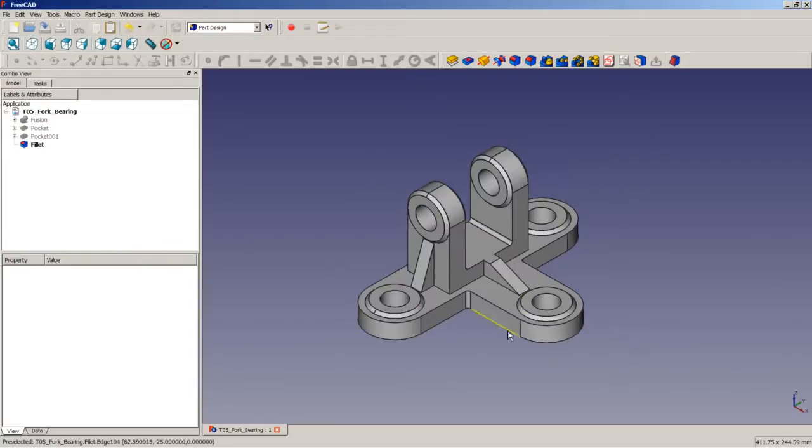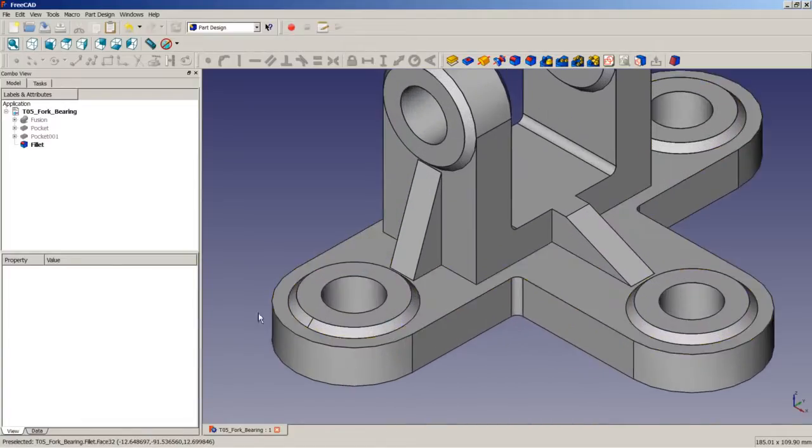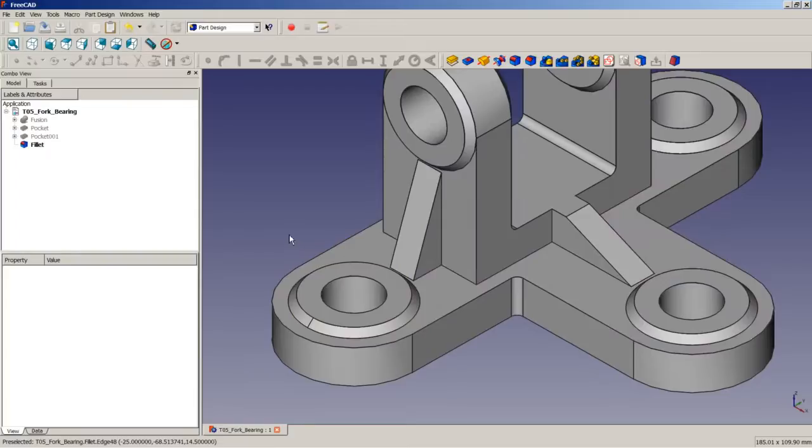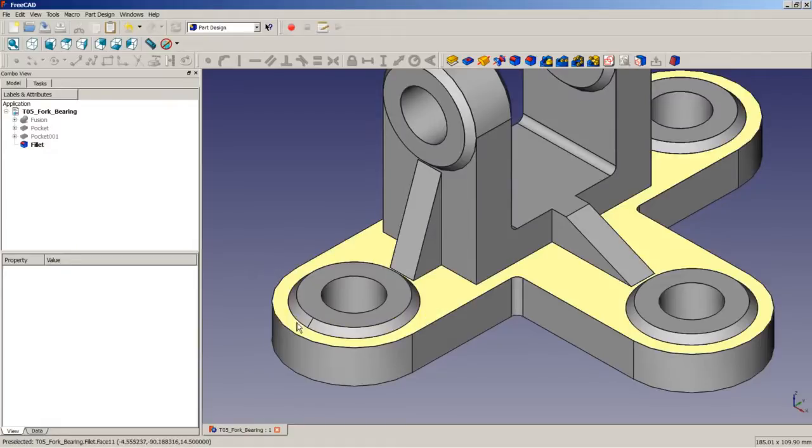The next thing you will notice is that if you would try to do a 3D model with, let's say, a cylinder with the outer dimension here, and then try to apply a fillet or a chamfer to this edge, you would run into a problem, because FreeCAD would tell you that if you try to apply this chamfer to this edge, there would be no material for the cylinder left.